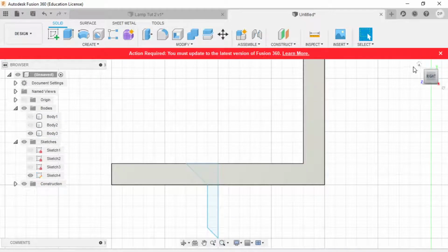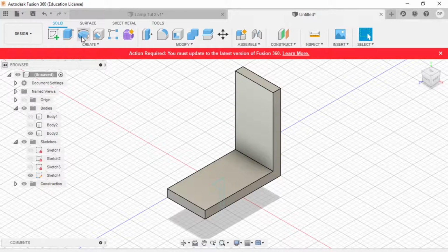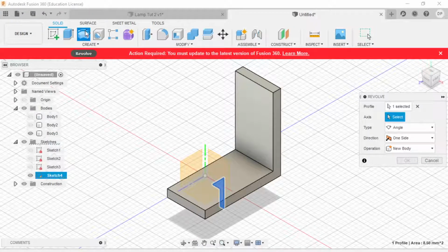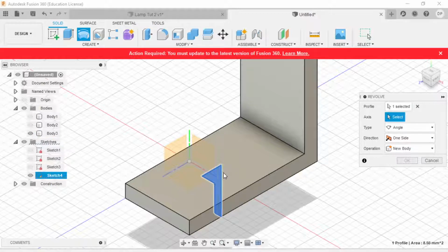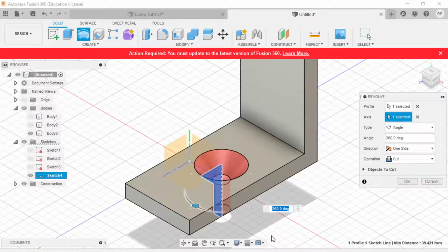I'm then going to press the revolve tool. This one over here. Press that surface we just had. The axis is the original axis that it revolved around, and so it's going to make a 3D version of that screw. Now, by default it's going to cut because it has determined there's an object inside another object.